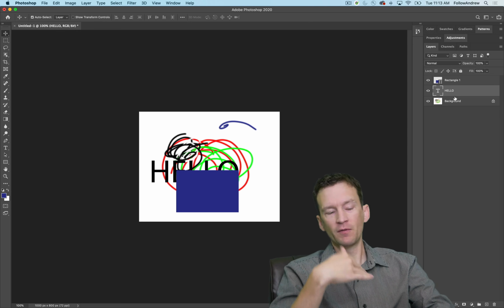Oftentimes you'll be zoomed in and you want to get back to 100%. There's a lot of ways you can do that. I'm going to show you a couple here. I can come over here to my zoom and I can just double click, punch in the keys 100 and hit return. That takes me back to 100%. Okay, so that's method one. If I'm zoomed way in, I can also hit on my keyboard the keyboard shortcut Command and then the number 1. That zooms me back to 100%. So that's method 2. The next method is if I'm zoomed in or out, I can double click on the zoom tool itself and take me back to 100%. So all of those 3 methods do the exact same thing.